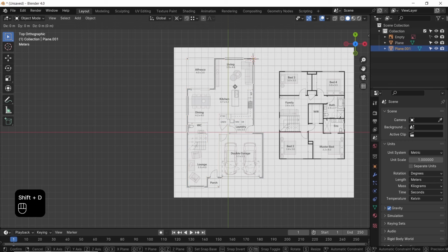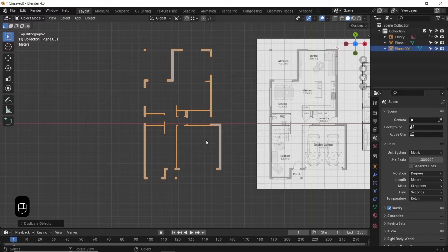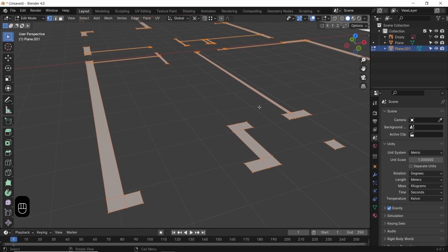Now that we're done with the drawing part, let's copy this mesh we made to the left, then in edit mode, and while on vertices selection, hit A to select all, then hit M for the merge command and choose by distance. This way you can delete any overlap vertices that you might have made while working. It's just for checking, and since we have 0 vertices removed, we are good to go.